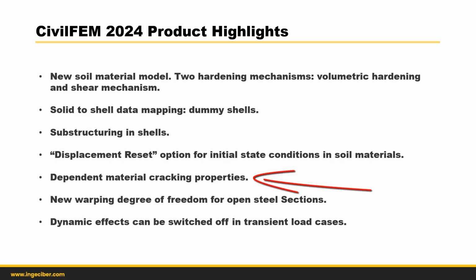Cracking properties can be constant, temperature-dependent, and time-dependent, that is, concrete age, for early-age concrete cracking, to consider material softening, or cracking stress due to elevated temperatures.